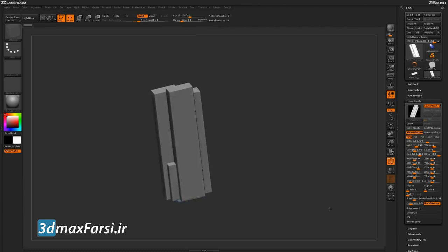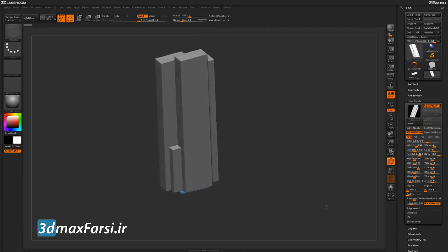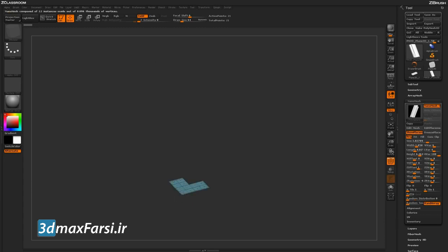So now that that is done, I want to come through and apply a second nanomesh to the existing polygroup here to create a lobby type structure. So now if I hover over a poly and simply click and drag, by default the insert nanomesh across all polygons is going to apply a new nanomesh to those actual polygons, and you'll notice that it has actually replaced the building part that I already had established.